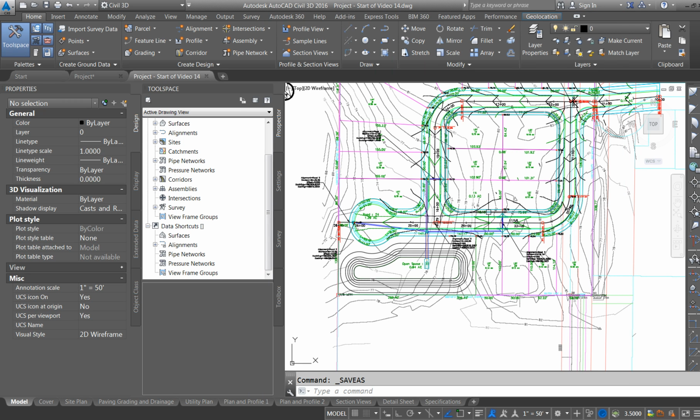In this video, we're going to continue on talking about storm and storm design. Now, just as a recap, to design the ponds, we typically use a method called the NRCS TR55 or TR20. We can also use programs such as the Interconnected Pond Routing Program, ICPR here in Florida, but a lot of the states use government programs such as HEC-HMS, which used to be HEC-1, that the Army Corps of Engineers developed, which are all free programs.